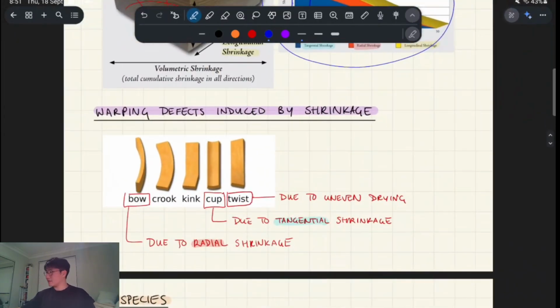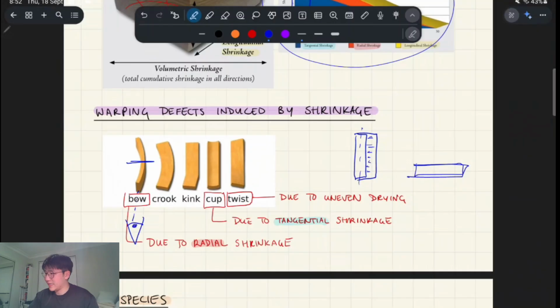We also have bowing. This happens when you have a fairly long piece of wood, say it's like that, right? So one side's flat. In the weak direction, if I'm looking straight onto it, so if my eye is like here, you'll see it bow out like that, in the middle, maybe like here. You can see this start to bow out like that. So again, it won't be flat if we're resting it on its minor axis like that. It won't be flat, and you'll see this little bit stick up, which is not ideal.